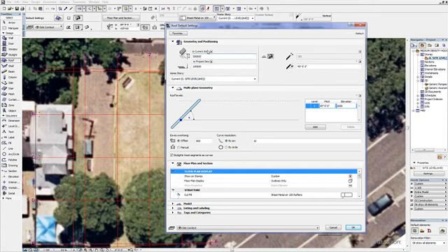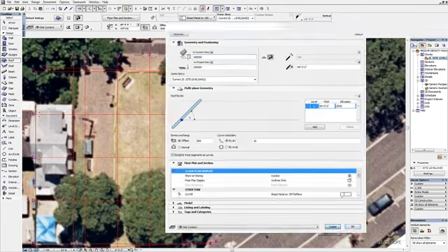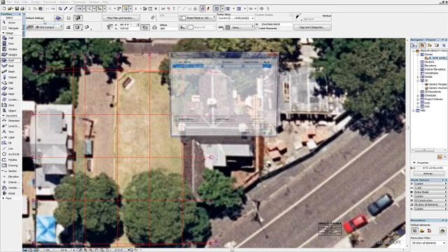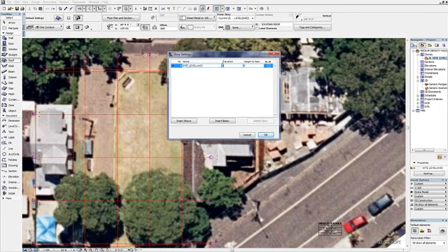For our particular project, the current story RL and the project 0 RL will be the same because we've started the project at a 0 story setting base. I'll just explain what that means: for the story settings, we've got only an RL level starting at 0.